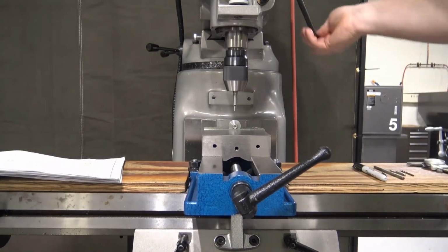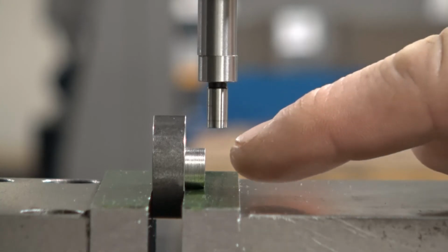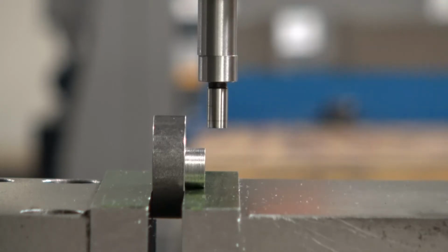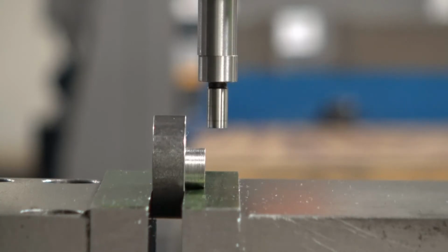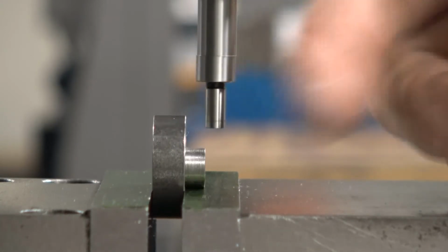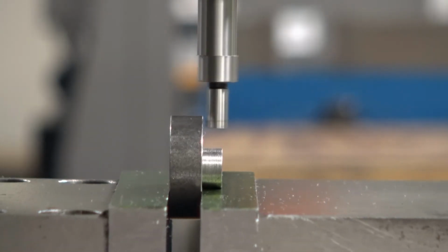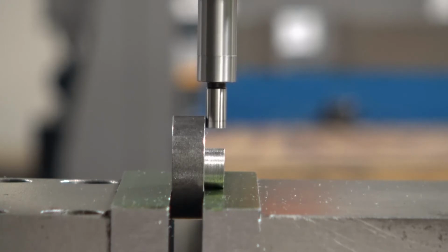Now we're going to bring the y-axis forward. We brought our y-axis forward. Bring our edge finder down so that that 200 thousandths, I'll call it the business end of our edge finder, is going to do our edge finding on this face, the front face of that 1-inch diameter cylinder. Like our edge finder to kick out a little bit so it's obvious when we get close. We'll come in nice and slow so that we can maintain our accuracy. And there we go, kick back out.